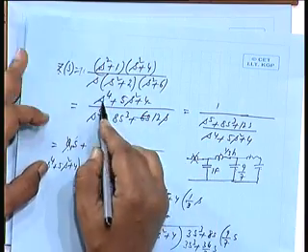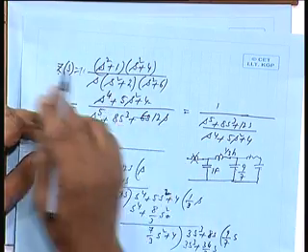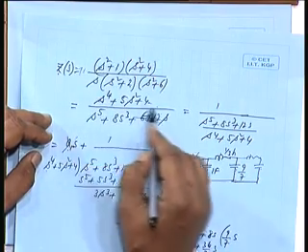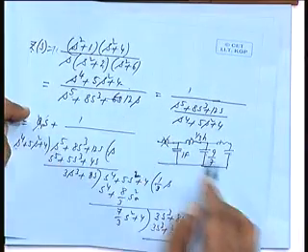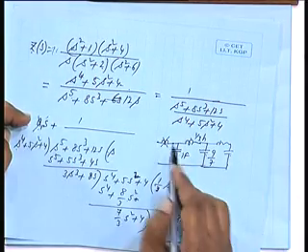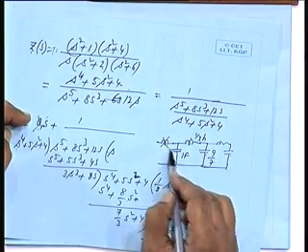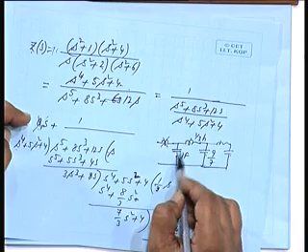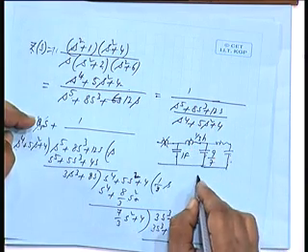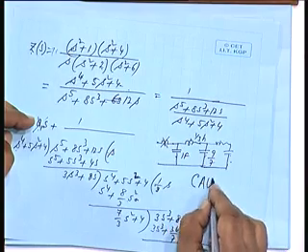So, if I go from the highest power of s, that is the polynomial is written in descending order of s, and then carry out the division, I get a structure like this, starting with an inductor in series, capacitor in shunt, inductor, capacitor, inductor, capacitor and so on. This is known as Cauer 1 synthesis.